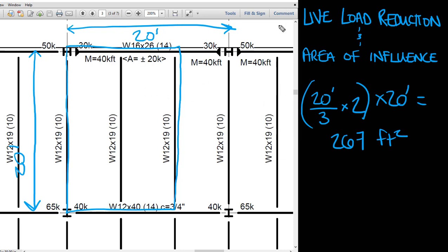And so live load, as you can recall, is occupants and their possessions. So what are the chances that this area is going to be completely filled with people and their possessions, this 267 square foot area? Well, it's not really that large of an area, so chances are actually pretty high depending on what type of building this is.